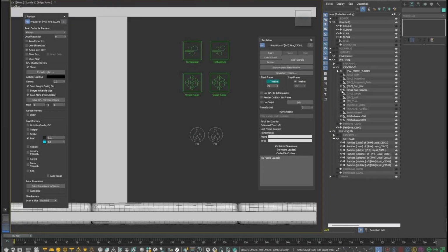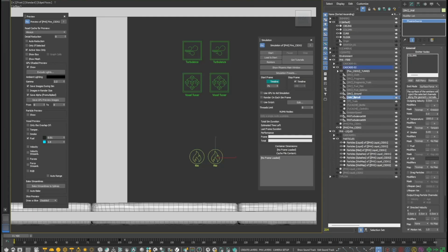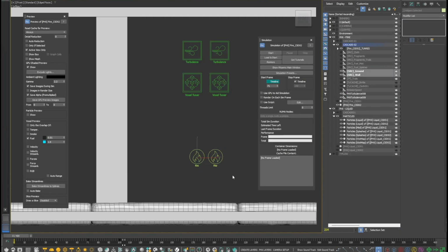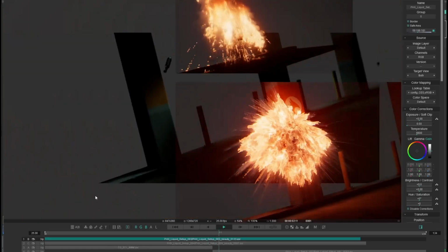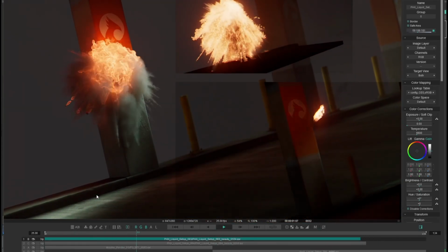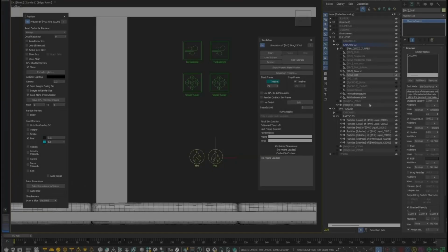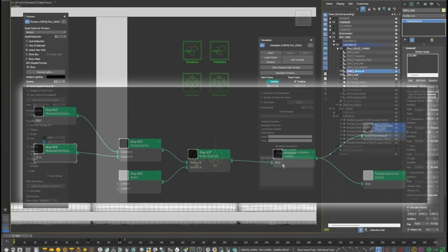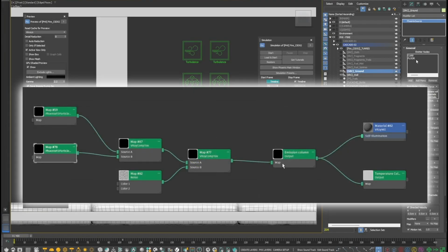And finally, the last two sources, the wall and the ground. These two take care of the burning wet spots. Similar to the previous two that were using the particles from the liquid simulations to add fuel, this could have also used the wet map particles directly as emitters. But since this project was intended to showcase a diverse set of options and possibilities, this time I decided to take a different approach. I added the collision geometries as emitters and masked the emission area and temperature using Phoenix particle textures.